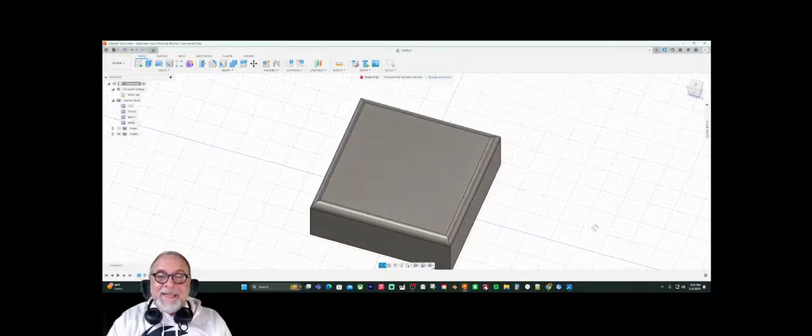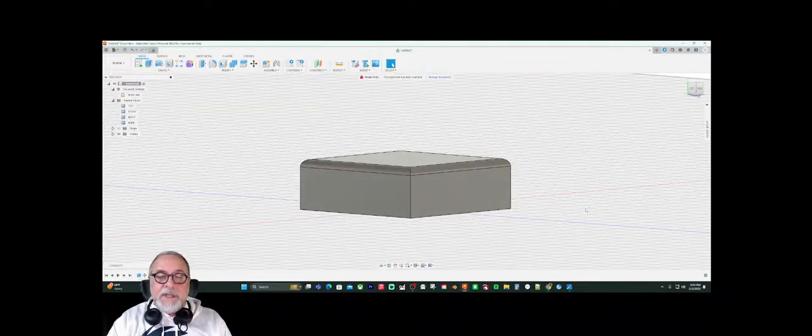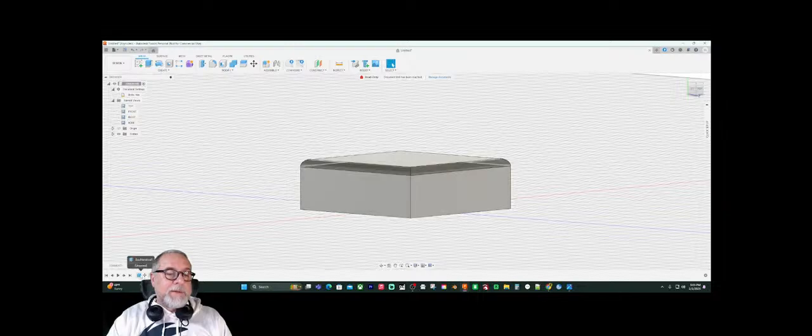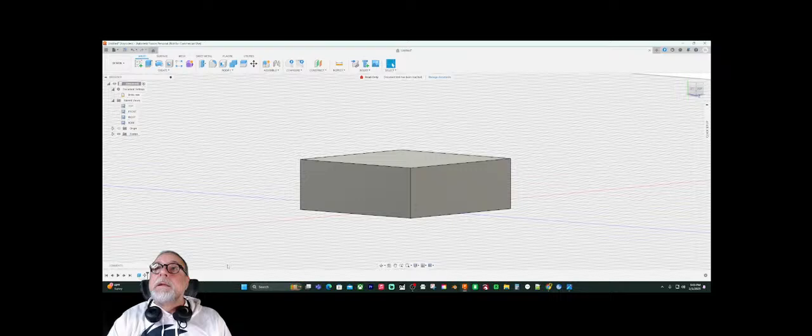What we don't like now is that it's still that boxy shape. So actually, remember how I was saying you can undo things? I'm going to show you that real quick. We can come back down here and select any one of these items. We're going to select this one, right click on it, and say delete. It's going to remove just that one step. It doesn't matter that it was the last step. It can be any step in that chain. You can delete it, and you can also move where that step is in the chain as well.